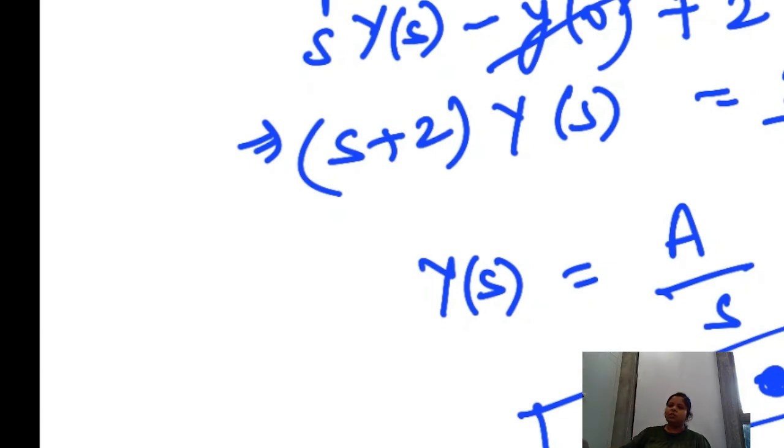You'll have these things always in control systems, because you will always want to find some kind of relationship between output and input. Let's say I want the speed of the motor, and I have some input given, let's say input current. What could be the relation between output and input? That determines my plant. The plant is represented by a differential equation, and you can always have a transfer function for the same.